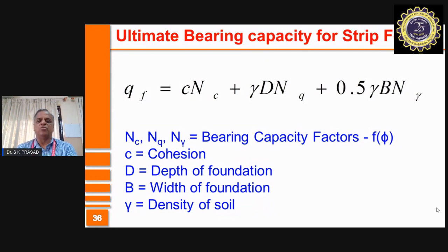Assumed bearing capacity is rather higher than the actual bearing capacity. Either some critical condition has happened because of heavy rains or maybe earthquake, or you design it for something and put extra load. You say that, okay, 3 floors this building is taking, and you build another 2 floors. Naturally, the provided bearing pressure is much more than the capacity, and that may lead to failure.